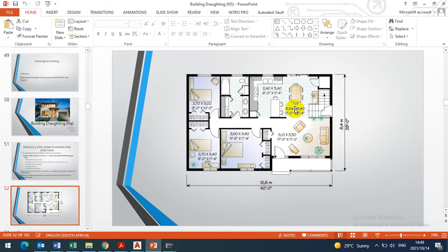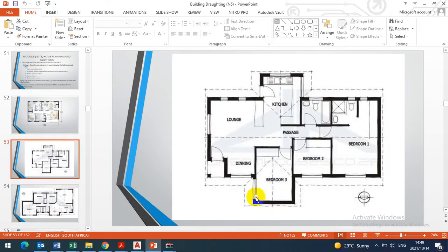And each floor plan needs to have all dimensions, internal and external wall thicknesses, internal room sizes, external room areas, the total length and the total width must be indicated. I'll show you. This is another example of a floor plan, not fully detailed because it's missing dimensions.